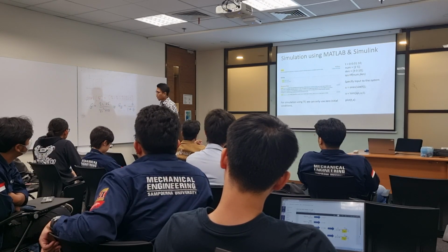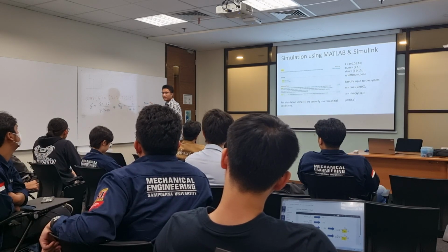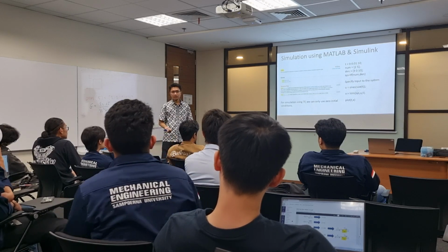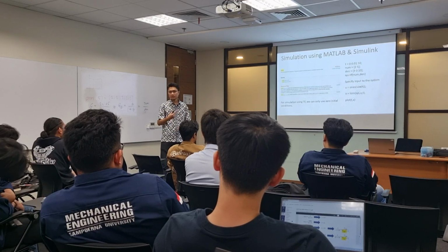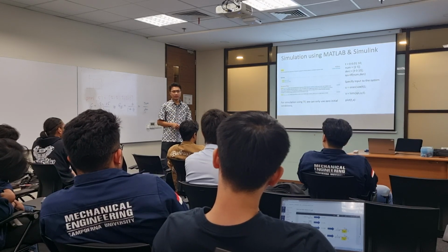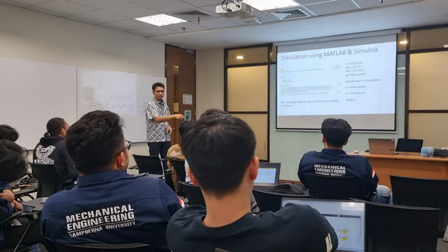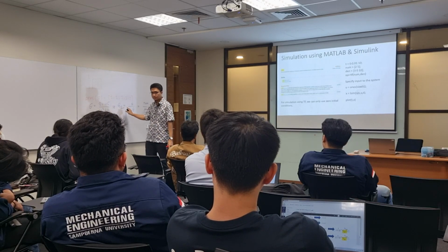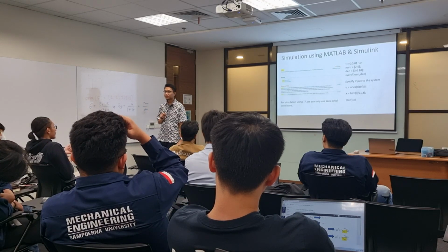like this. Once you obtain this, you obtain the new numerator and denominator, right? Yeah, you replace this into the MATLAB, and then you obtain your closed loop transfer function. You simulate again, that's your closed loop system response. Okay, so if we use the M file editor, you have to write down the closed loop transfer function on your own. You write down the result.